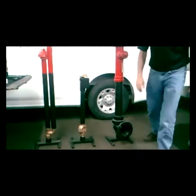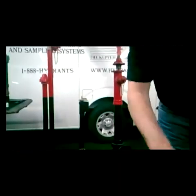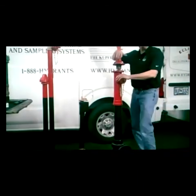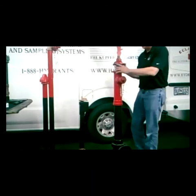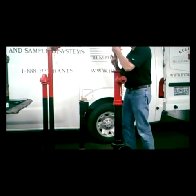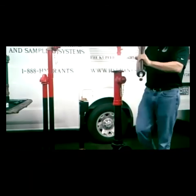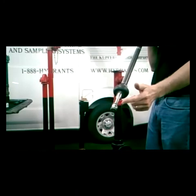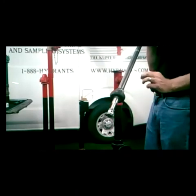To do maintenance on this, it's very simple. I turn the water off to the water line. I open up the hydrant to get that plunger to come up out of that seat. It makes it easier to pull the guts on this one. And then I have 4 bolts on the top. I take the bolts off, and I can take off the whole operating rod. And the only maintenance that we do on this particular one is we have a rubber seat, and we have O-rings on the nozzle down here, 2 O-rings. So this is the maintenance on the number 2.